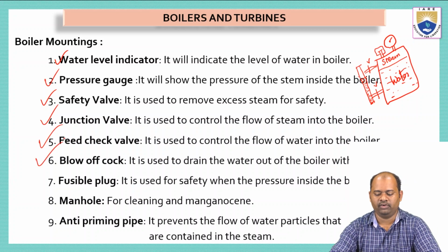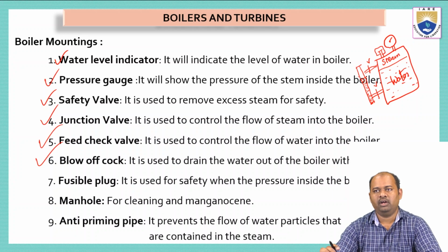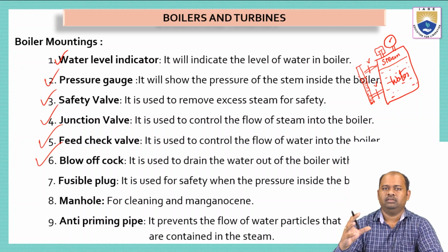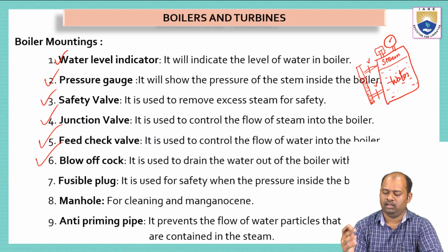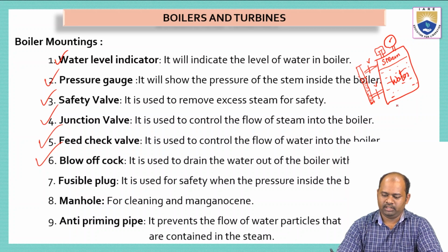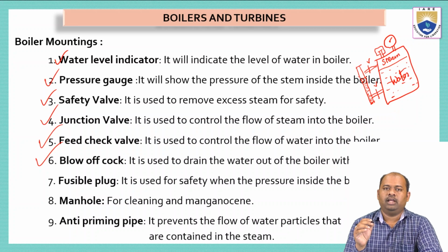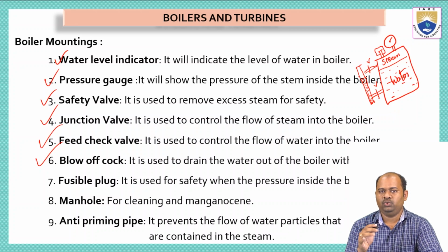And then the blow off cock. The blow off cock is a device which is used to drain the wastewater that is present inside the boiler. Whenever there is a boiler, the boiler has to be cleaned. In order to clean the boiler, we should have some kind of opening, because the entire boiler is filled with water.